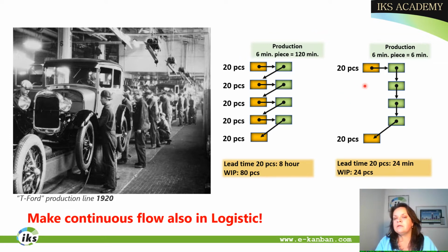So 100 years ago we really solved this issue. We put this in continuous flow. We connected all the dots. We synchronized the times, and the output is that we continuously move part by part, and you see that the lead time for 20 pieces is only 24 minutes instead of 8 hours.